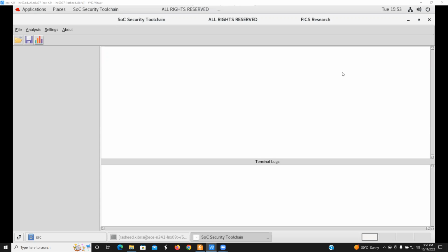In my previous presentation, I extracted the control FSM of the ASCON cipher core from the RTL design that was written in Verilog HDL. In this demo, I will analyze the synthesized gate level netlist of that core, more specifically the flattened gate level netlist of the ASCON cipher. I will use my developed FSMx-Ultra tool to analyze the gate level netlist and provide us the state transition graph of the control FSM present in the gate level netlist.